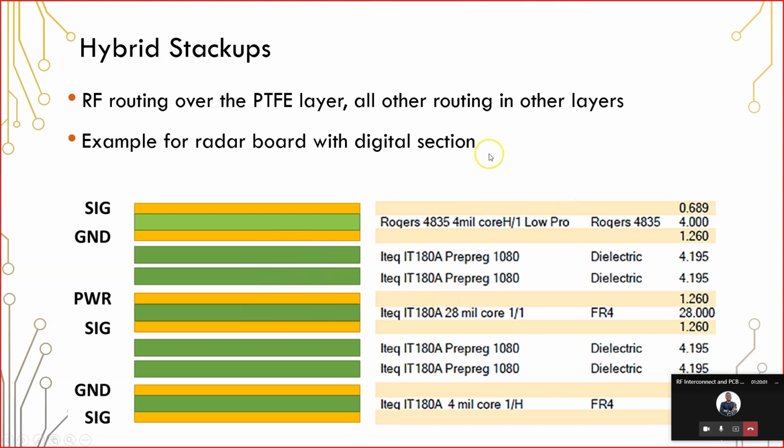And that's something that you are going to need more of when you have a lot of digital signals operating in the PCB. So that's a bit of a topic for another webinar on power integrity. It's a bit more of an involved topic, so we won't go too deep into it. But just remember, as you pack more and more very fast digital signals onto this board, you would need to bring power closer to ground to provide enough decoupling and capacitance.